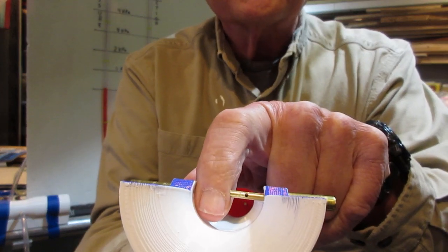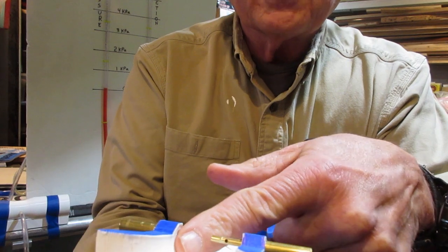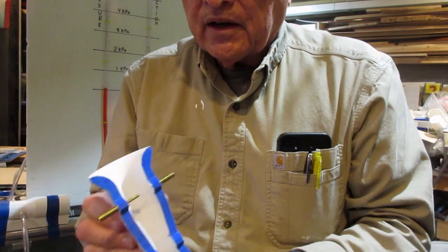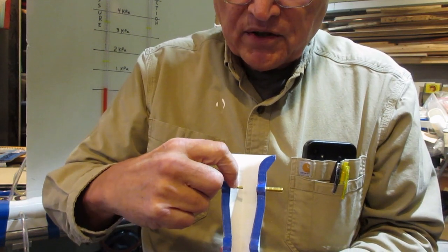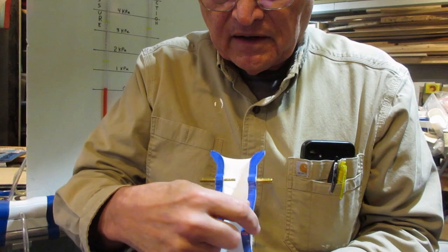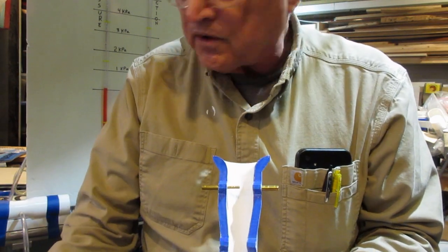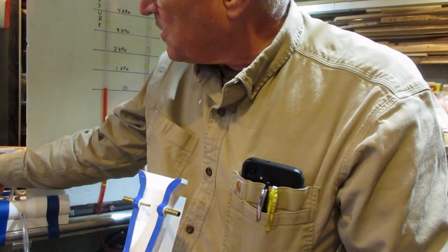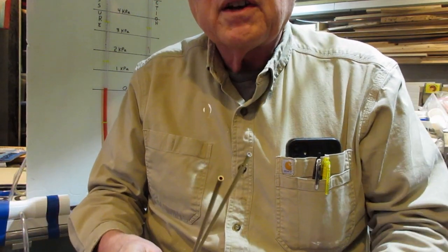I have no idea if it's focused. And then this is just stuck in, so it measures the pressure on the side. And that gets you pressures, the dynamic pressure from that little hole, the static pressure here, and then you get the same measurements there, and you know the cross section here, you know the cross section there, you can do all the math.